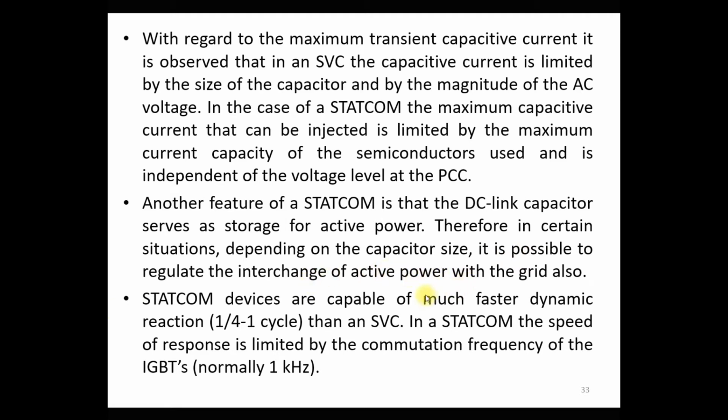As we discussed in the last lecture on the theory of the STATCOM, when the DC link voltage of the STATCOM becomes lower than the required voltage, at that time we generate the output voltage of the STATCOM with its angle slightly lagging behind the voltage angle of the bus voltage, so that we can transmit active power from the system to the STATCOM, because active power is transmitted from higher angle to lower angle.